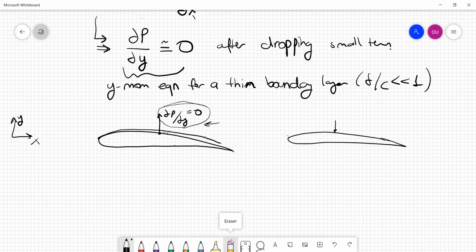But the result that you get, even without the viscous solution, will be very close to what you get with the inviscid solution. There will be some minor differences though, due to some flow properties that we're going to discuss within a few weeks. For example, one flow property is that if we have this thin boundary layer, at high enough Reynolds numbers, the boundary layer goes through what we call a transition process.